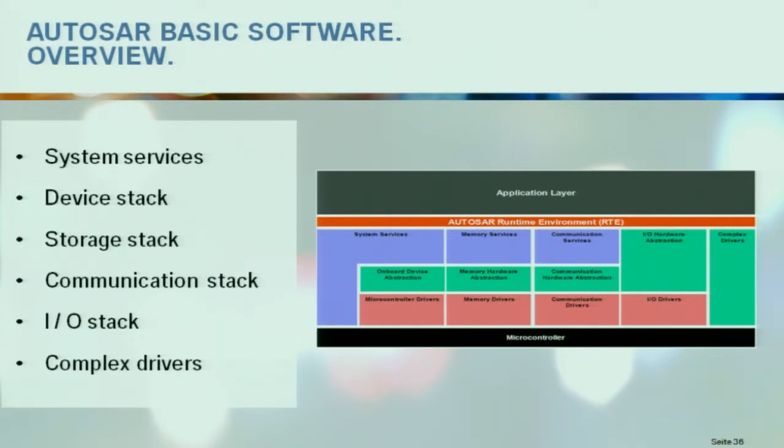Then the communication stack handles all the bus systems, even the local SPI, for example, and also the CAN bus, FlexRay bus, and so on. The I/O stack, meaning if you have some AD converter or digital I/O, is handled via this stack.